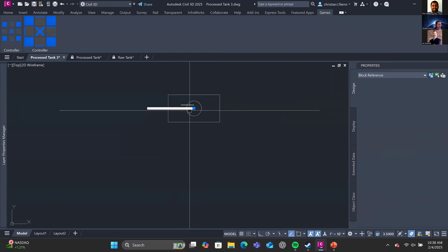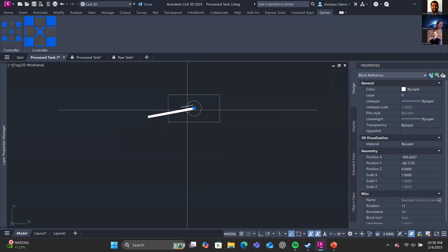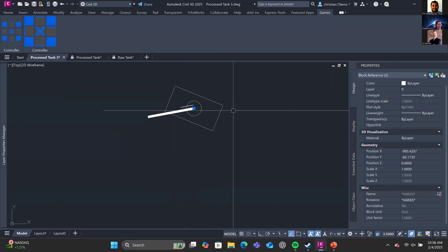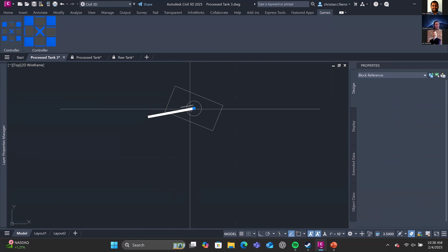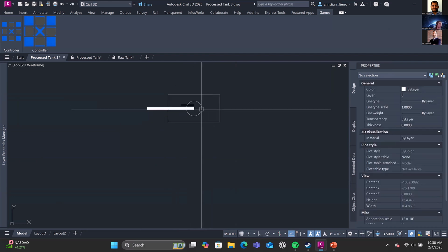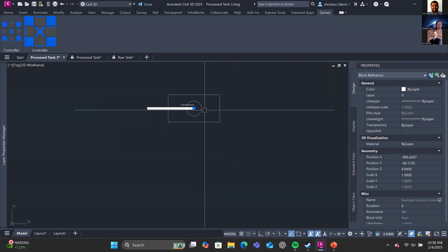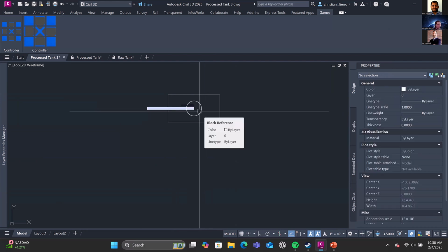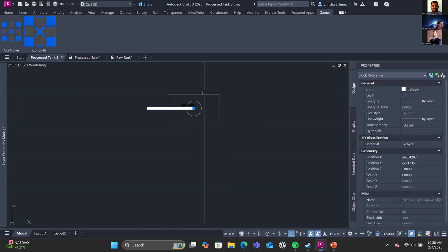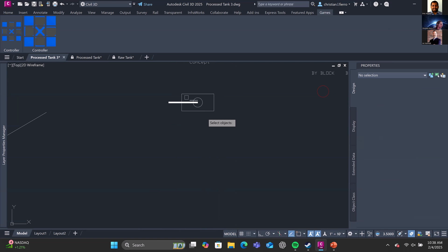So I can kind of look at here and say, okay, well, I like this. This is working fine. But one thing that I don't want is to have two different blocks doing two different things. Because if I look at both of these, their rotations are completely different. And whenever I want to move one object, I have to then select another object to then move it. So this is the point of having a dynamic block. So what I'm kind of figuring out for myself is what I probably want to do is incorporate a rotation parameter, maybe a move parameter, some additional parameters, and select these different blocks to do a specific function. So now I can look at this. I can, let's say, go to copy.